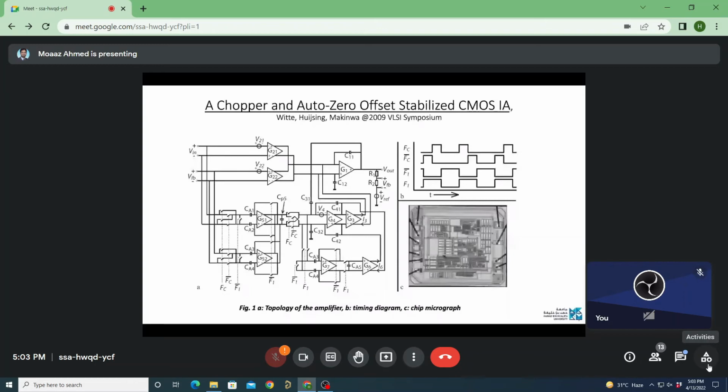The difference in their output currents drives the integrator built around this G4. This in the middle in turn drives a transconductor G3. The G3 output current feeds the output stage that you saw, in the form of G1. This is the output stage, G1. So essentially, this is a 3-stage amplifier.